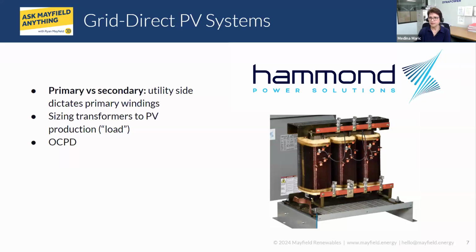If I may add to that, Jeff, harmonic content has to be taken into account with power conversion equipment. If you're dealing with thyristor rectifiers or even IGBT solutions in large systems, as Dynapower is dealing with, you are absolutely right. We do have a lot of switching elements in our configurations, and the lower the number of pulses that we are producing on DC, the higher the harmonic content. That harmonic content is defined by IEEE 519, and there are recommendations in terms of the transformers.